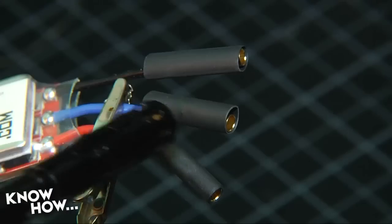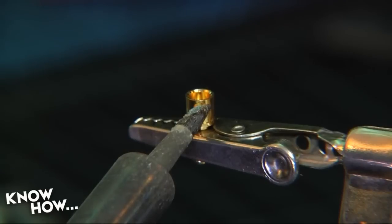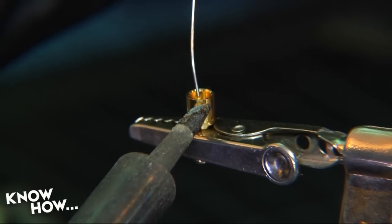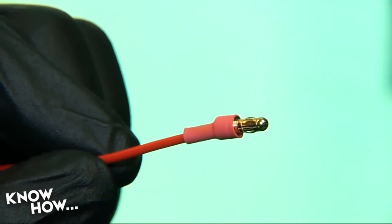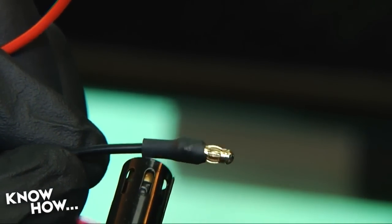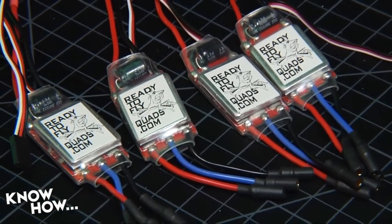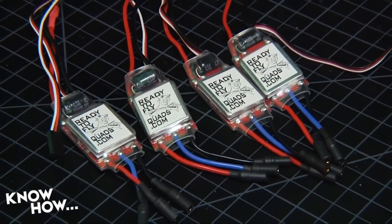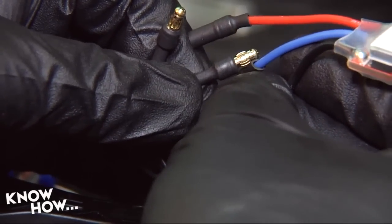Check your work, then insulate the bullet with 3/16-inch heat shrink tubing. The power leads of each ESC should already be stripped and tinned, and we can leave them at their original length. Solder each end into a male 3.5mm connector and insulate as before. I suggest using red heat shrink tubing for the positive connector and black for the negative. Unlike the motor leads, swapping power leads will destroy electronics.